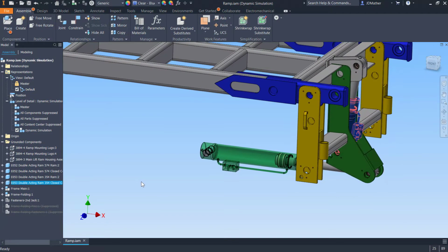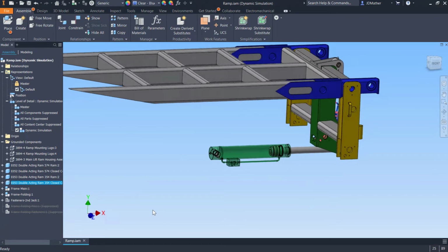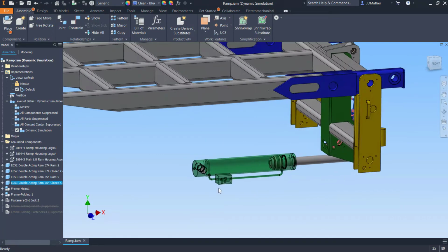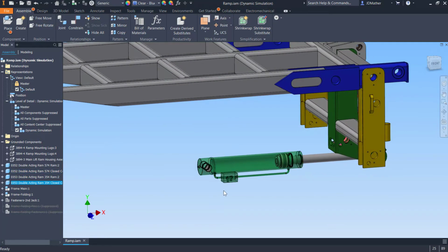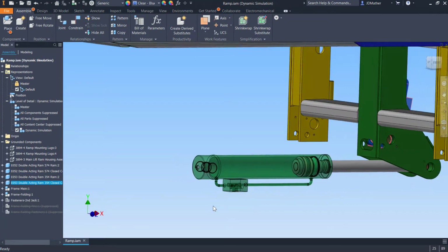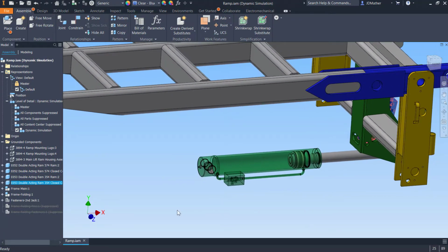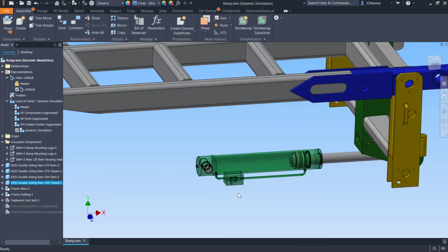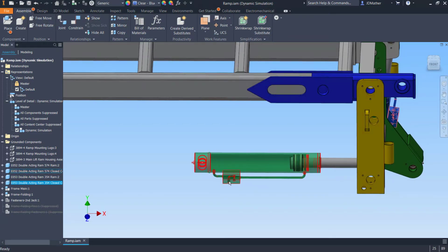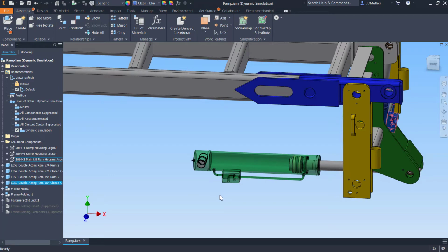Now as we go through this, we're going to have to be really disciplined in order to avoid getting lost in how we put this assembly together. So there would be some hydraulic lines coming out the bottom of this manifold, and those hydraulic lines could catch on something as the truck drives over an obstruction. And so I think I prefer to move this cylinder, reverse it the other way around, so that the manifold is on the top rather than on the bottom. And in our part there was room for that to occur, so that's what we'll do.